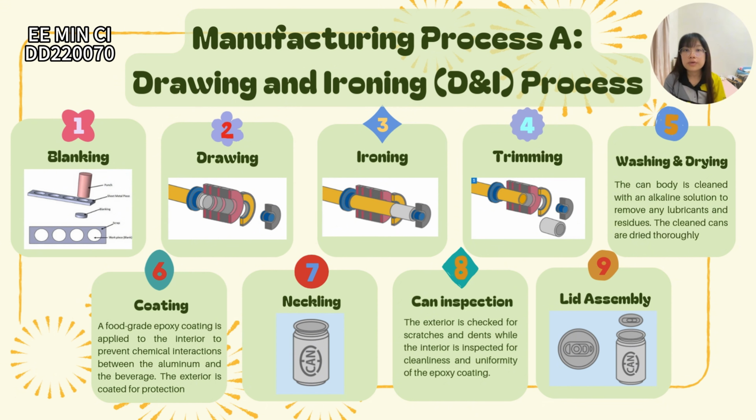The can body is cleaned with an alkaline solution to remove any lubricant and residues from the manufacturing process, and then the clean cans are dried thoroughly. The sixth process is coating, in which a food-grade epoxy coating is applied to the interior to prevent chemical interaction between the aluminum and the beverage, and then the exterior is coated for protection and prepared for high-speed printing.